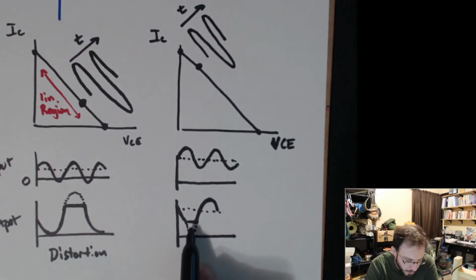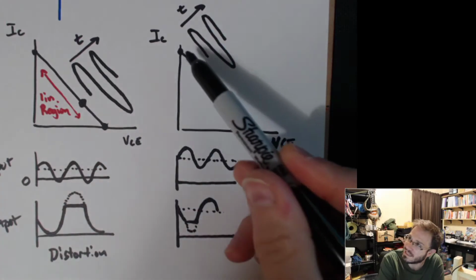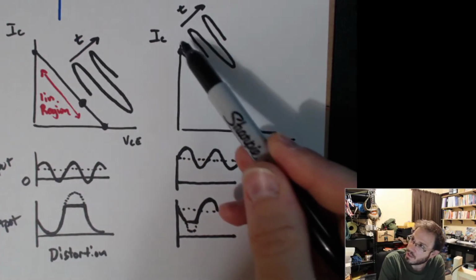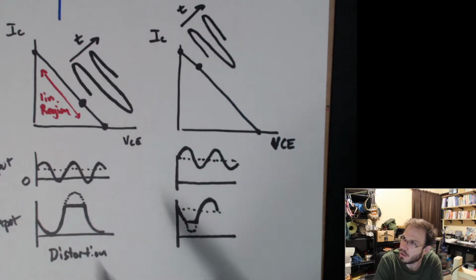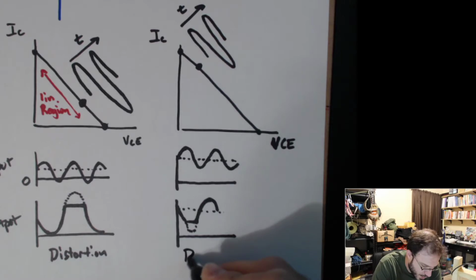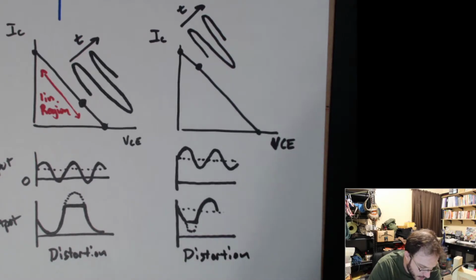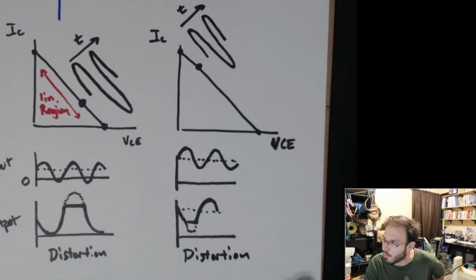We should have completed this, but we hit saturation when our applied signal caused the Q point to shift into the saturation region. So again, this leads to distortion, which is great for a guitar, but terrible for us.